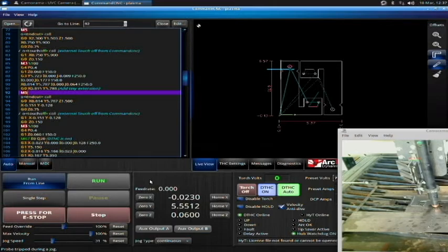It will not be the correct voltage feedback. So the torch will run too close to the material during the section that's already cut. So if I want to prevent that, I can turn the torch height control off. So if I hit manual, torch height control off,